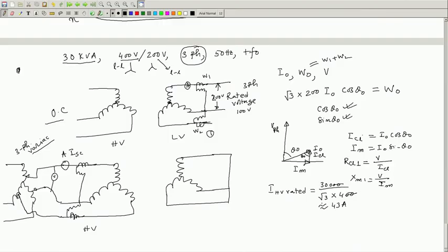So, you have to choose an ammeter which can read 50 ampere, say, and similarly wattmeter current coil. But for the line to line voltage, the voltmeter rating should be very small, maybe 5-10% of 400 volt. 5% of 400 volt is only 20 volt. Voltage required will be pretty small. So, that rated current will be circulated. Secondary will also carry rated current like the primary. So, that copper loss will be there.